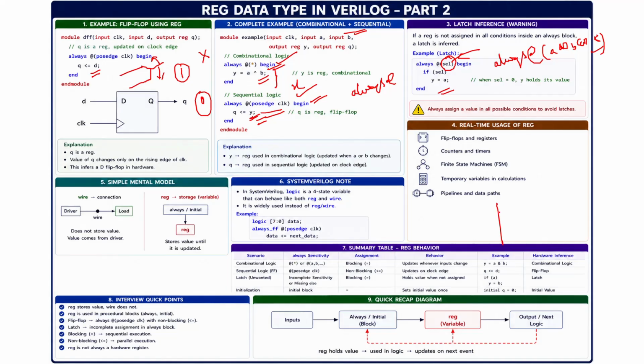So I told you about the XOR gate, how you are designing it with a 2 by 1 mux. So this is my 2 by 1 mux. Okay, A, B, two inputs I am giving, one select line, one output I am getting. So for the XOR gate, A, B are two inputs and then the output: 0, 0 gives 0; 0, 1 gives 1; 1, 0 gives 1; 1, 1 gives 0. Then I am designing the multiplexer in this way.